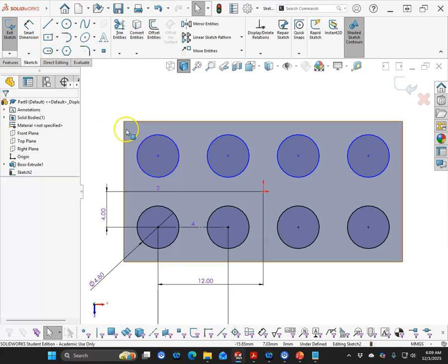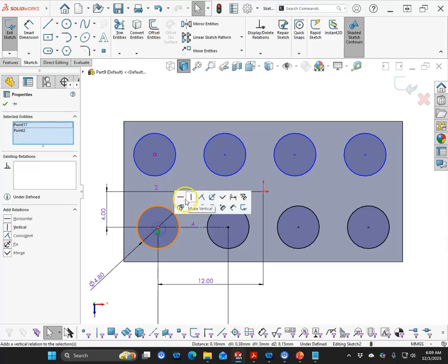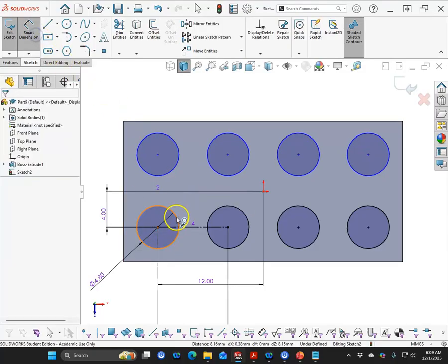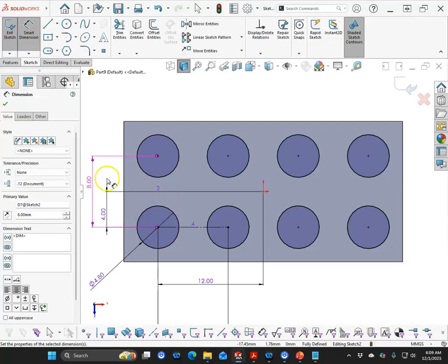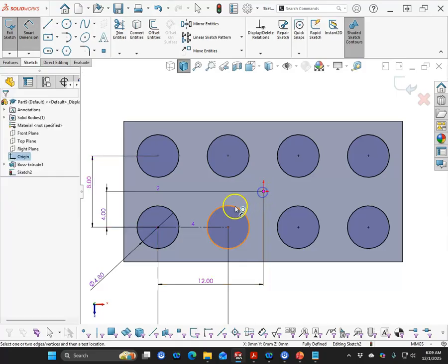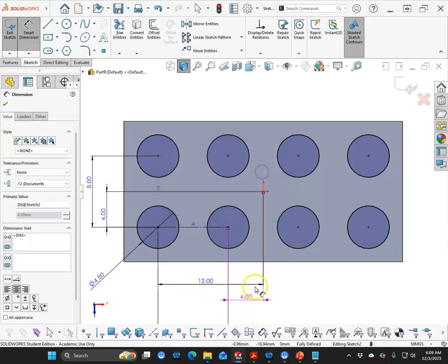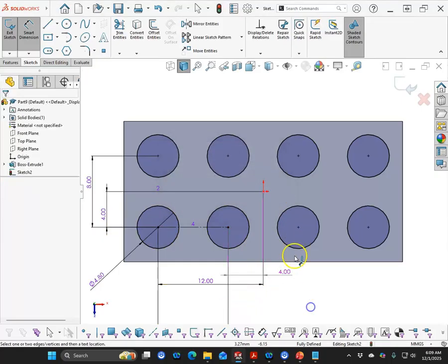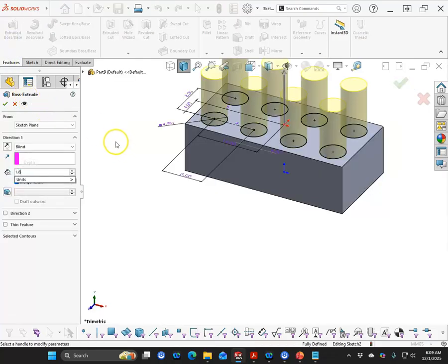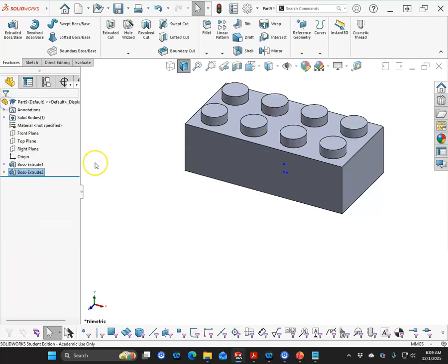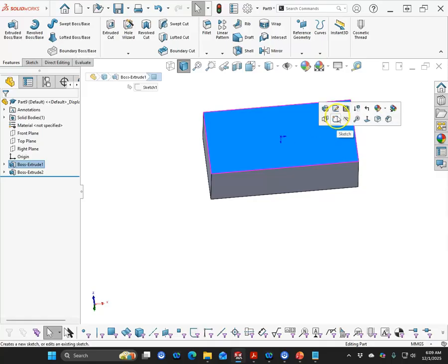Oh, I didn't add a Y spacing, so if we move those, we can kind of see the way that they shift, and I moved it just enough. All right, so to verify my number, I would put that in and just let it be driven as what becomes a reference dimension, and that becomes 1.8. Okay, so that gets us a good start on our geometry.